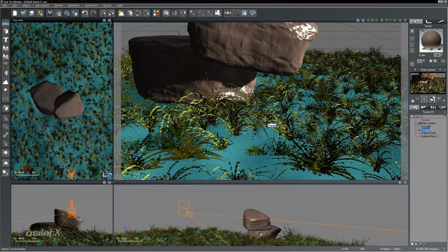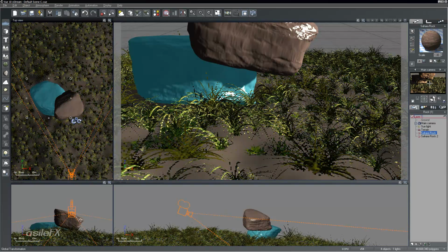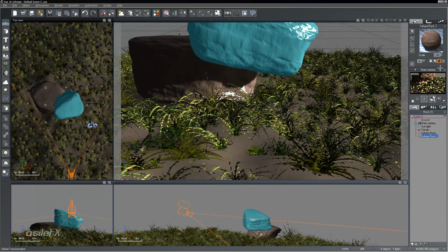Now if you want an object to ignore those population rules, there is an option to ignore ecosystems. So if we don't want these rocks to influence that decay near foreign objects, we can just turn that on, and this is in the Object Properties panel.